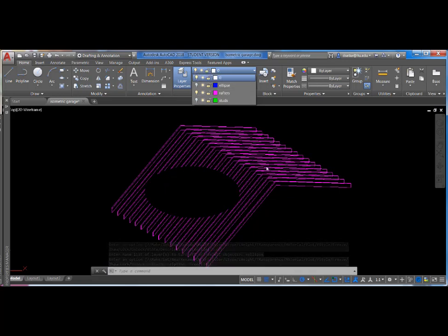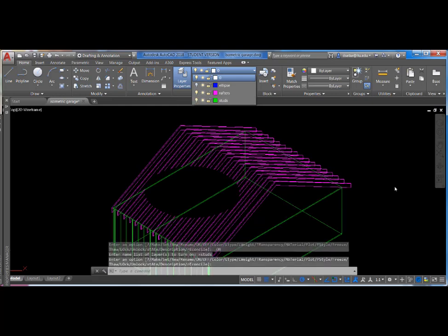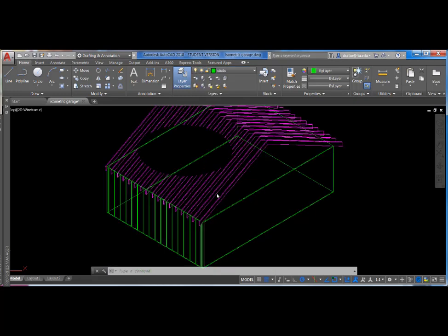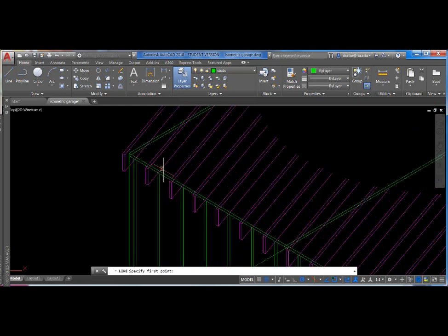We also have roof joists. Okay, I'm going to go ahead and draw those roof joists on the stud layer. Okay, so the roof joist will end up being next to the roof rafters. So if I draw a line, I'm going to come in here and specify this point. It starts right next to the joist. I'm going to go up 9.5.